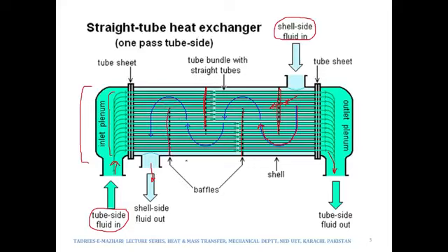So the fluid is being flown in a particular direction, and you would have realized by now that this is being done so as to increase the heat transfer rate between the two fluids. And the baffles in fact induce turbulence, and turbulent heat transfer is more than the laminar heat transfer. So the baffles are used to make sure that the fluid makes a good contact, and in fact it induces turbulence which enhances the heat transfer rate.